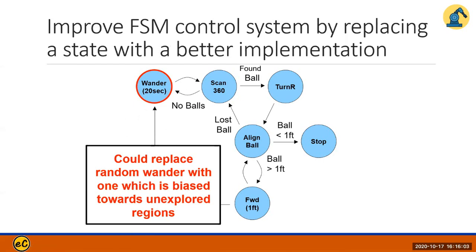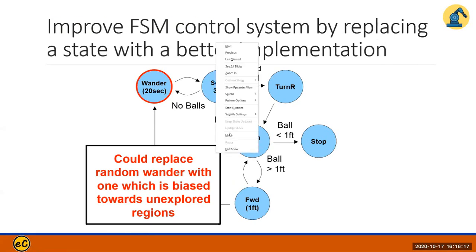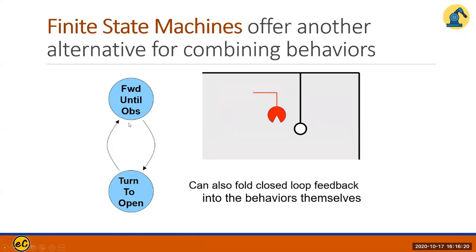And that actually is a control design. And this one actually is only one proposal. You can change to a different state machine, but the core computation is still the same. Still continuing the movement until obstacle, still forward until obstacle, and turn until you see open. So it's a displacement and a rotation, two different actions.